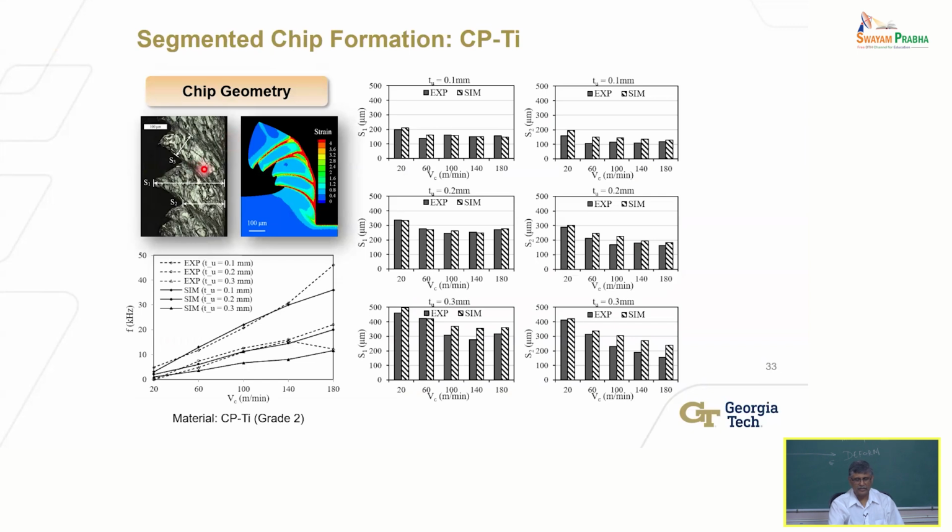Even in these regions, when you see something that is very, very white on an optical microscope, which is easy to get access to, it appears white because the optical microscope is unable to resolve it. That to me points that there may be something there, maybe nanocrystalline structure, possibly. It could also be amorphous, but possibly nanocrystalline. Then you have to dive into some other deeper, higher magnification probing technique, like transmission electron microscopy or EBSD.